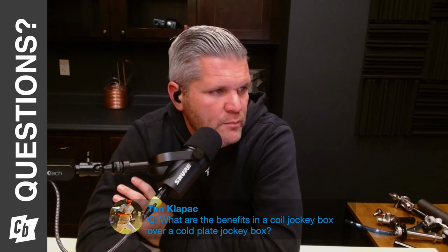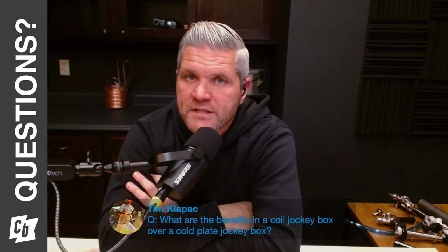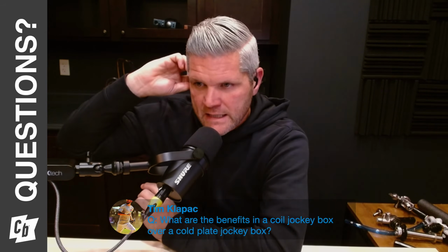All right, any other questions out there? Oh, one more. Here we go. What are the benefits of a coil jockey box over a cold plate? Okay, so the inside of a cold plate only has about 11 feet of stainless steel in it. So you're getting about 4 ounces of beer cold at once.